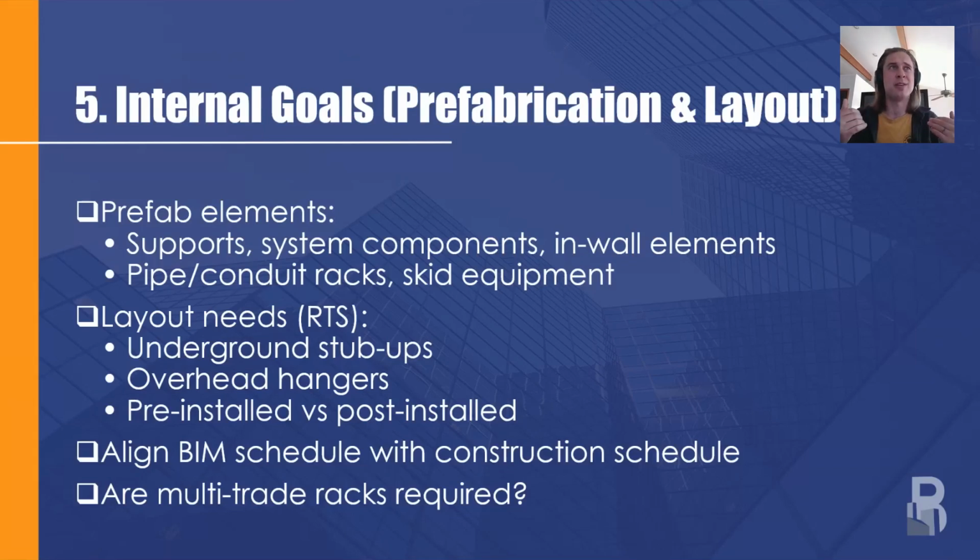So if you think about construction sequencing, that's really early in the project. You're essentially coordinated while steel is getting erected. While there's a ton of advantages that come out of pre-installing those anchors, it's a lot to ask from the coordination team as well. So understanding what's locked in the model at that point in the project versus what isn't, and maybe there's a blended approach there as well.